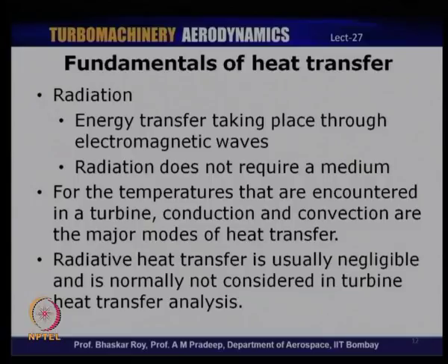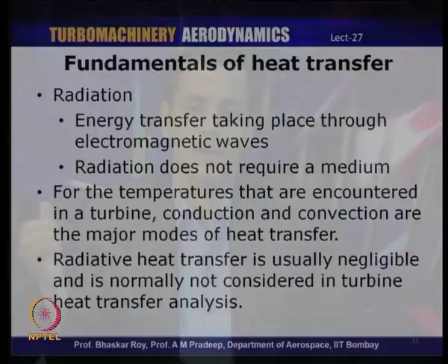But for the temperatures that we are looking at in a turbine, the major modes of heat transfer are conduction and convection, and radiation is of course present. We cannot say it is 0, but compared to the heat transfer taking place through conduction and convection, radiative heat transfer is usually negligible, and it is not usually considered significant in the case of turbine blade cooling and heat transfer in a turbine blade. So, we will be restricting our discussion on heat transfer in turbine blades to conduction and convection.